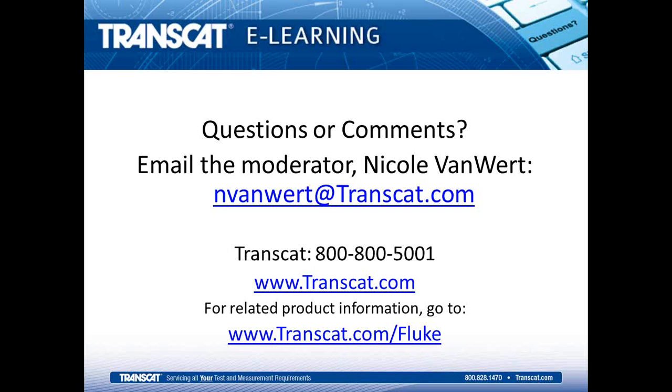One thing you've got to remember with thermocouples is that their uncertainties can be on the order of a degree, maybe half a degree. If you're around ambient conditions, you're not asking too much of it. So when we relate all those uncertainties we were looking at earlier to the capability of a thermocouple, they're maybe not quite as big of a concern. So just make sure you're not trying to get a couple of millikelvin out of a thermocouple, and that'll help.